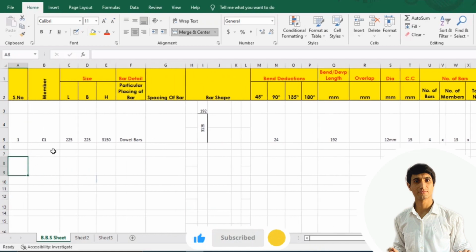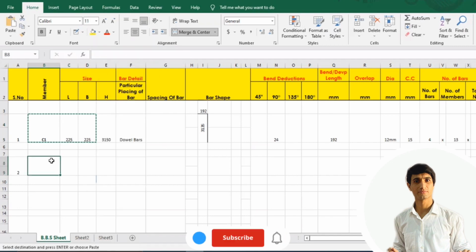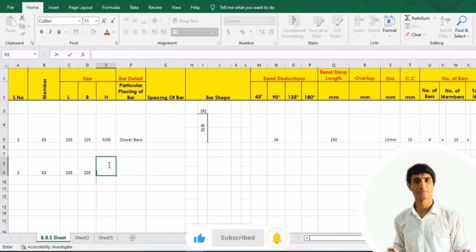Hope you understand. Number 2, we are going to find out the rings as well. We have different spacing for the rings. We have rings on h/6, and we have rings on the mid, so both of these we will find out separately. Up till this position it is okay for us, and now we know what the h/6 value is. The h value is 3000 divided by 6, which will give us 500, and we have h/6 at the bottom and h/6 on the top, so it will give a total of 1000, where we need to place these rings with a spacing of 150 I think.